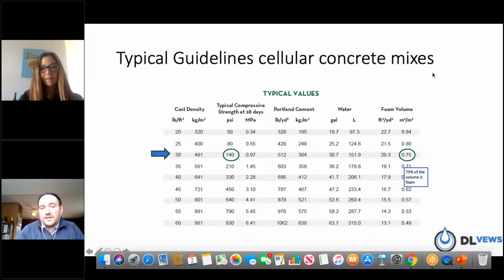And it's giving you something that has a compressive strength that's significantly larger than your average compacted backfill. And so that's why cellular concrete makes a good annulus fill material. To answer one part of your question a second ago, it's just a really good material to give you a nice compressive strength and a void space that is otherwise hard to get to, right?